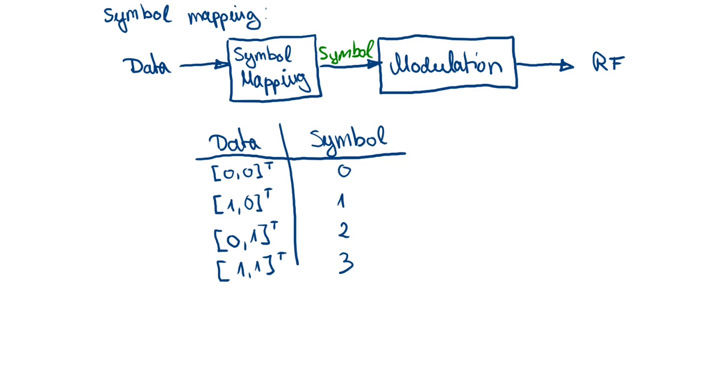For example, if you imagine that here is the boundary between the digital and the analog domain, and the modulator works solely in the analog domain, then each symbol, for example, can represent a voltage. But in the modulation techniques which we consider here, the modulator is mostly implemented in the digital domain.